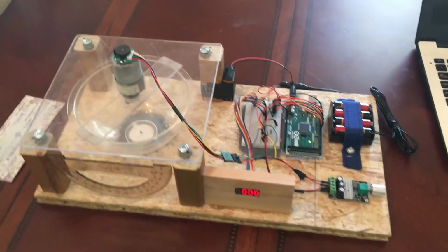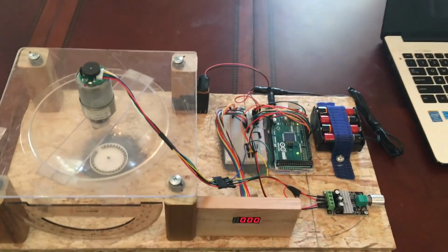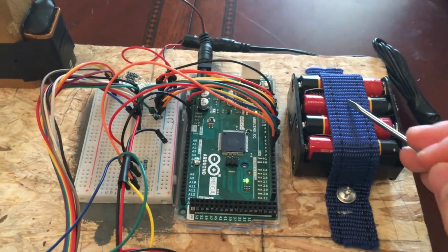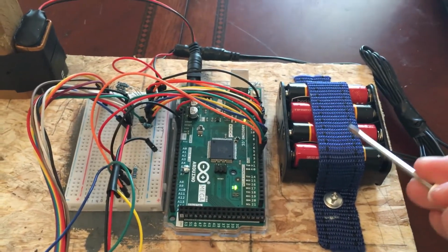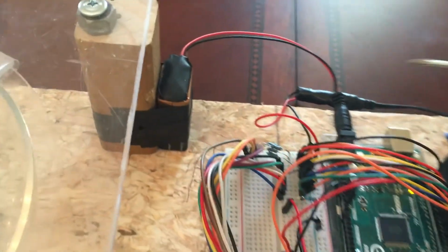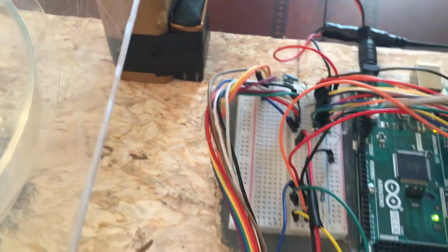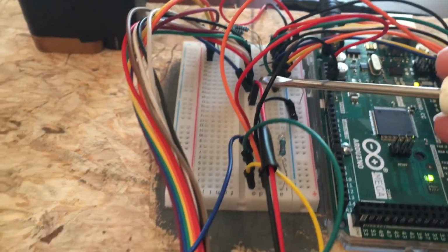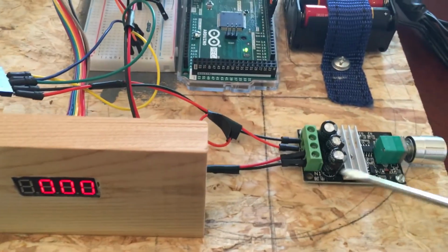So I'm going to be explaining the wiring and circuitry behind this whole machine. We start off with our battery pack right here, which has 8 1.5 volt batteries for a total of 12 volts. The current flows through this positive wire to the breadboard and powers this whole line. The current flows through the resistor into this positive wire, which goes to the potentiometer.